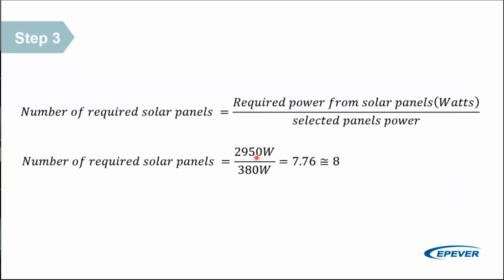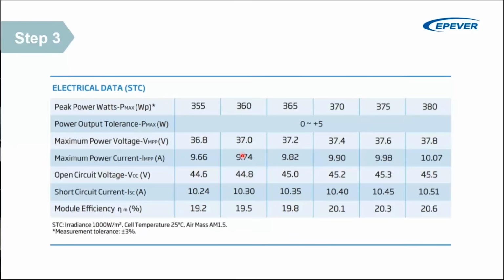Well, so I know the number of the panels that I need of this type, and you can see the short circuit current, the ISC, and open circuit voltage, or VOC, here. For this example, I have assumed that the nominal voltage of the panels is 24 volts. You see a different voltage, VOC, open circuit voltage here, so it's not a nominal voltage. Nominal voltage is confusing for PV panels, and it is just used for classification. It's not a real voltage you are going to measure.